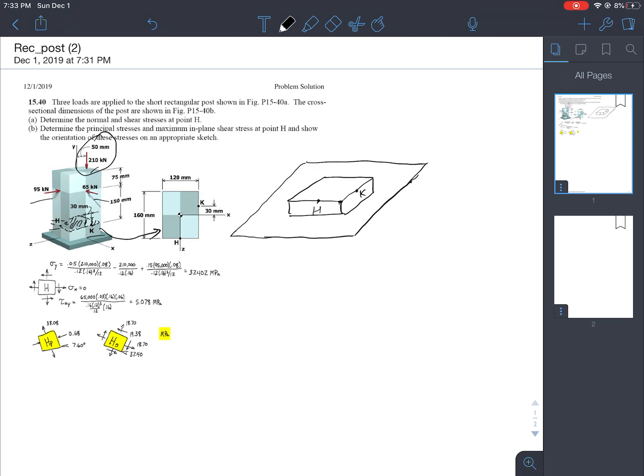I'm going to move these forces first. This is the axial force right here, moved to the middle of the section. By moving that, basically I introduce a moment. Since it's shifting to the x direction, I actually introduce the moment in the Mx direction.